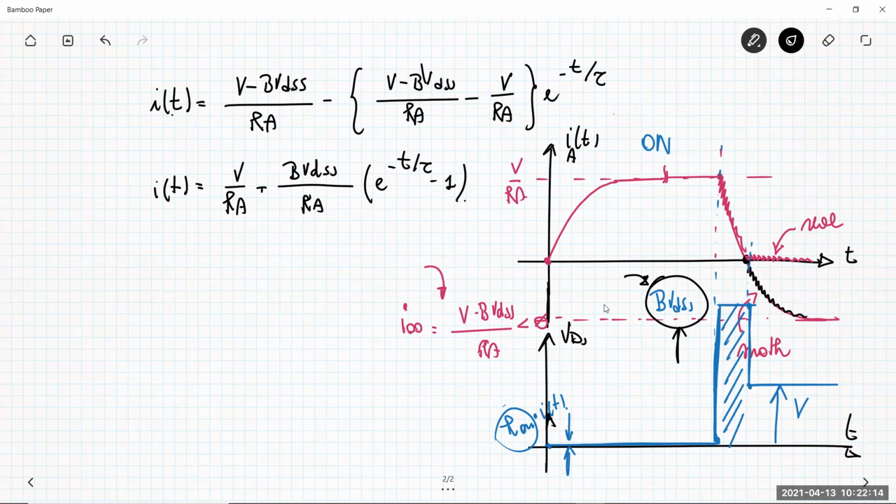This is always related to the fact that operating the MOSFET, or even the diode, whatever semiconductor power device you can have, exactly at the breakdown voltage increases the current flow into the MOSFET. So there is a phenomenon which is a typical thermal phenomenon: it increases the temperature of your devices. The thermal time constant typically is not so fast.